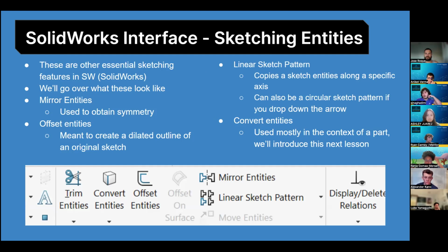Especially when you're manufacturing something, it's easier to work with, and it doesn't crowd your dimensions. So you know that if you change one dimension, it changes the other, and it doesn't make you do the extra work. You want to look for the easiest way out of the sketch so that it's easier to read. Kind of similar to how Ryan was talking about coding, right? You want to use the simplest code so that it's readable and so that you can navigate through it. It's the same thing for SolidWorks or Onshape on CAD. Your dimensioning should be simple, it should make sense, and it should be something that you can read and interpret.